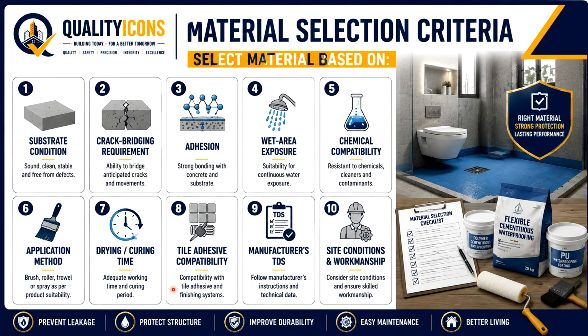Another very important consideration is tile adhesive compatibility. For example, if a waterproofing material is applied over the slab, but the tile adhesive is not compatible with that system, debonding of tiles can occur later. Finally, always follow the manufacturer's TDS, the technical data sheet, and the approved project methodology.